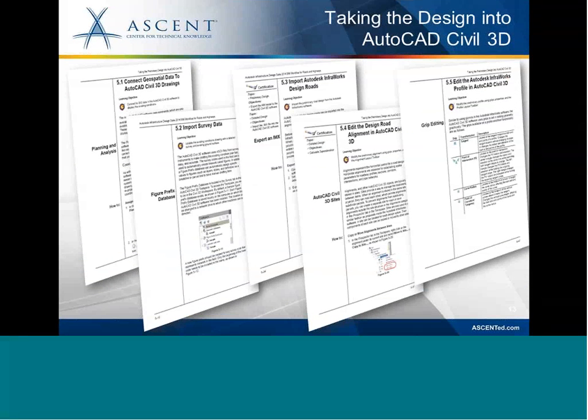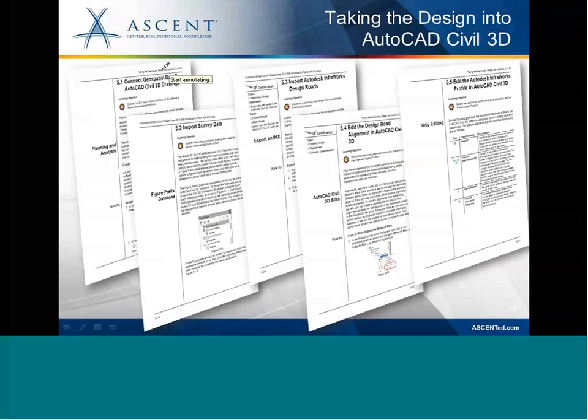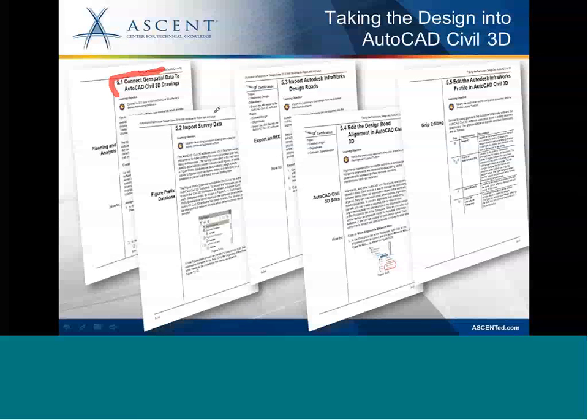Once you have a really nice model inside of Autodesk InfraWorks, we then take that information that you've designed and pull it directly into Civil 3D so that you don't have to lose any information. And so what we do is we start with connecting the geospatial data by using the Map 3D tools inside of the Planning and Analysis workspace of Civil 3D and connect up to the same data that we had available in InfraWorks. So we connect to those SDF files, we connect to the image file that's in the background, we connect to the DEM file.